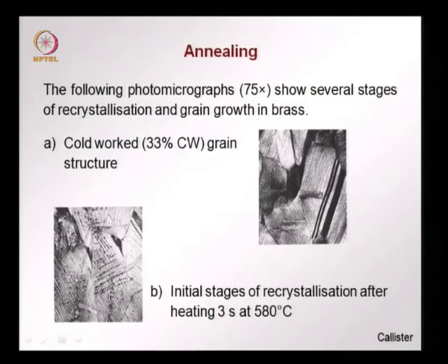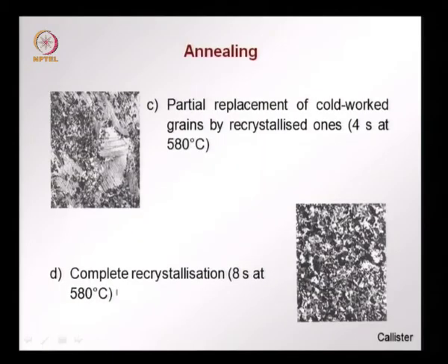These small imperfections which are starting are actually crystals which are starting to grow. We see a decrease of the slip lines being prominent, and we have the small crystals now growing. This is the initial stage of recrystallization. Now we continue.